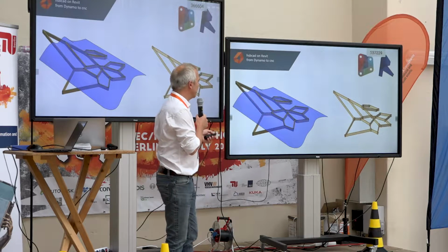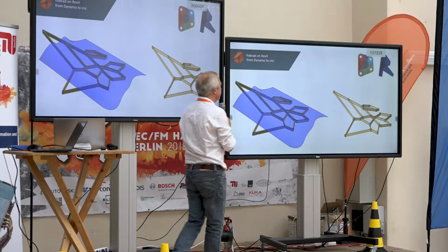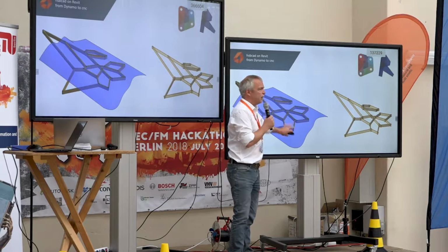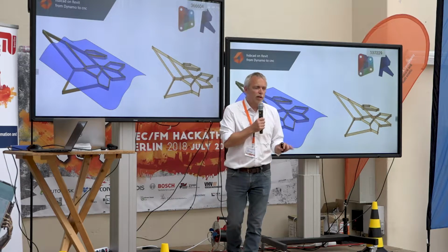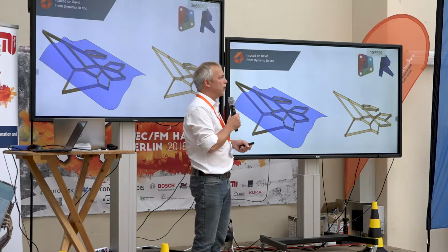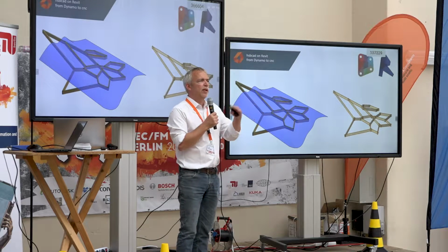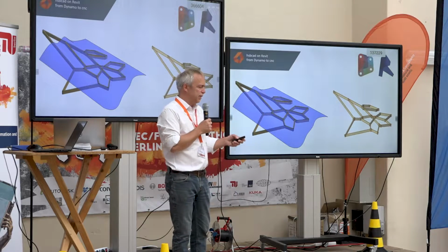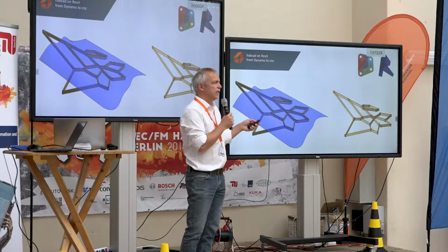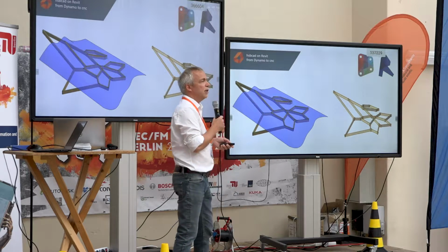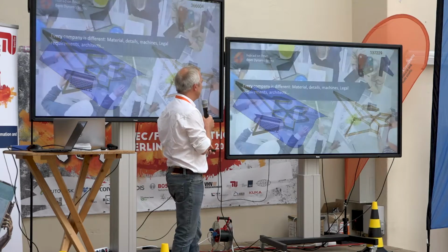We do have, because these tools in Revit, they're just based on normal void cutting, like we have in Revit. You can define voids and void families that can cut other pieces. So we actually simulate the operations that are done by the CNC machine. So these void cutters, they actually can be driven by Dynamo.